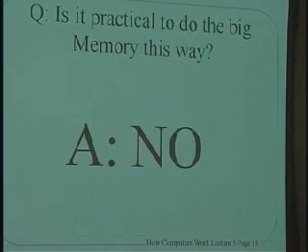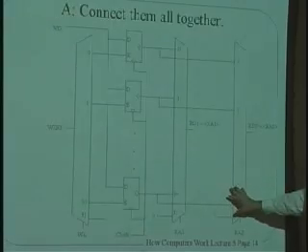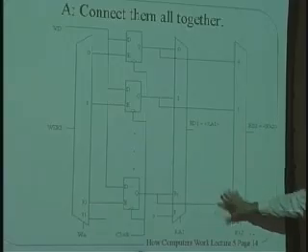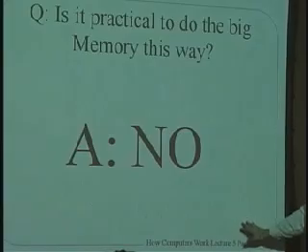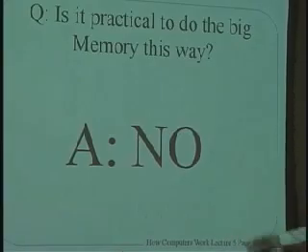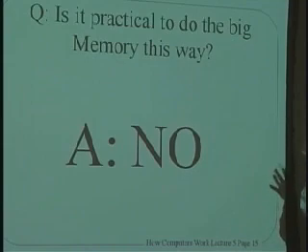That's crazy, right? This architecture that we have before, let me actually go back to this. This is fast, okay? It turns out this is a small, fast memory. But if we want to do a big memory, and we try to do it like that, it would be ridiculously slow. Like even slower than the RAM actually is inside of your PC, because the selectors would have so many inputs. The fan-in would be so great that the amount of electrical charge you would need to get data through this monstrous thing would be so large that it would take forever for that charge to build up to get the data out. Okay?